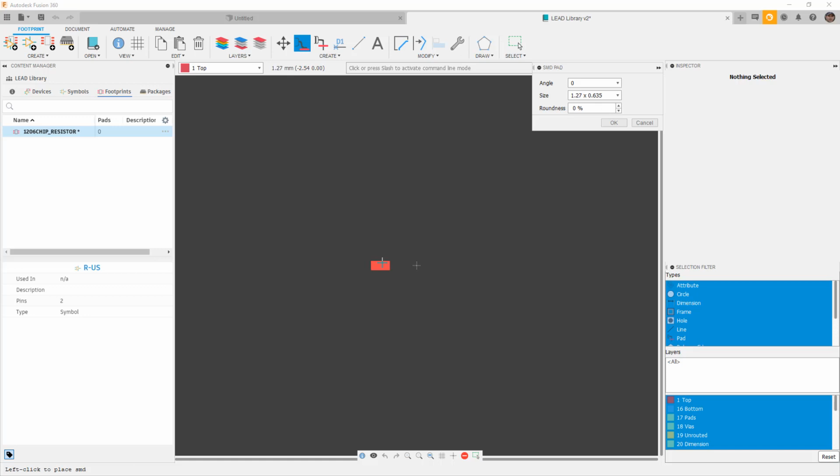All right, so we have to, again, remember exactly the size we need. I'm going to set this at 90 degrees. And the pad that we need is going to be, in this case, 1.6 millimeters by 0.9 millimeters. You can use this drop down and you can oftentimes find ones that are pretty close. So you see here 1.67 by 0.8. That's likely going to be the standard.